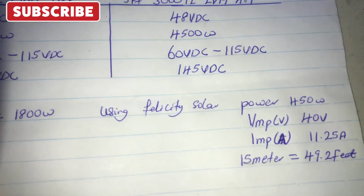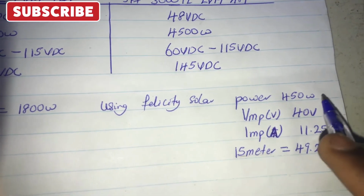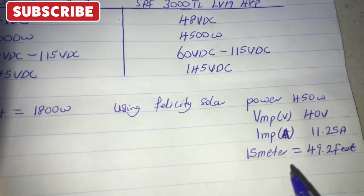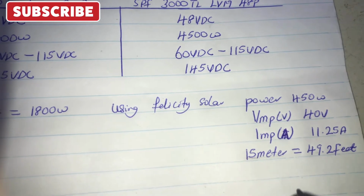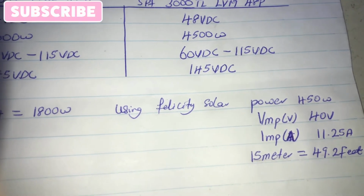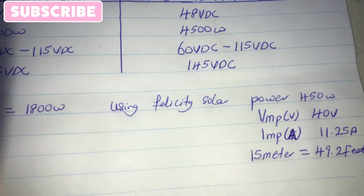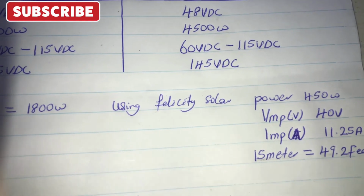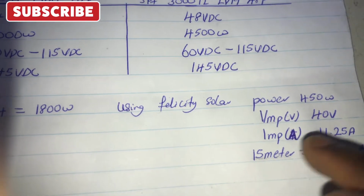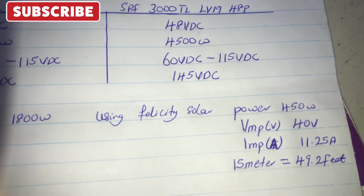So from here, I'm using Felicity Solar. From the research I did, Felicity Solar 450 watts has the power of 450 watts, then maximum power voltage, that's the maximum voltage it will produce, is 40 volts. This is not the open circuit voltage, please. I am not using open circuit voltage for this calculation. Open circuit voltage is the voltage the panel produces on no load, when nothing is connected to it, when it's just idle. But this maximum power voltage is when it's connected to a charge controller.